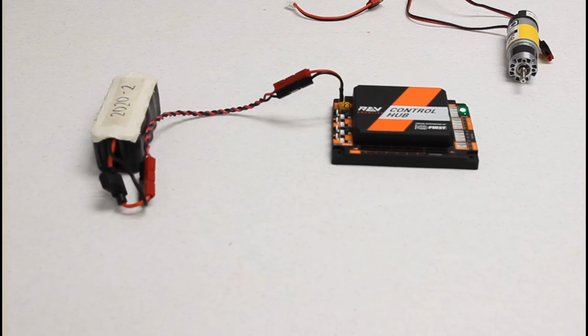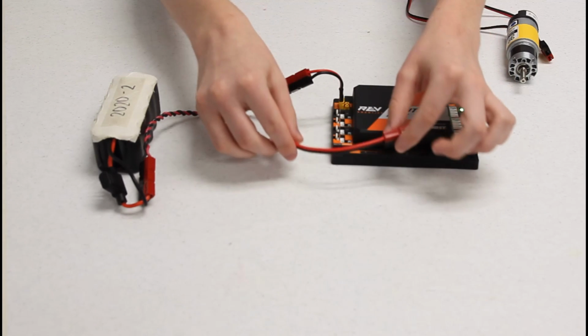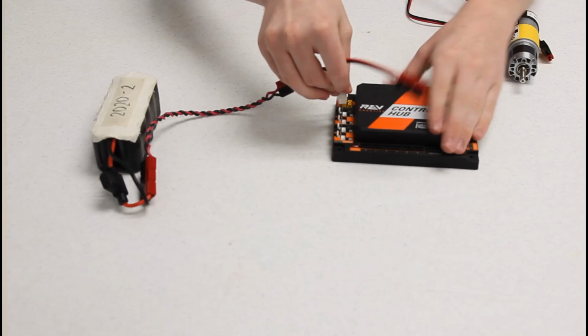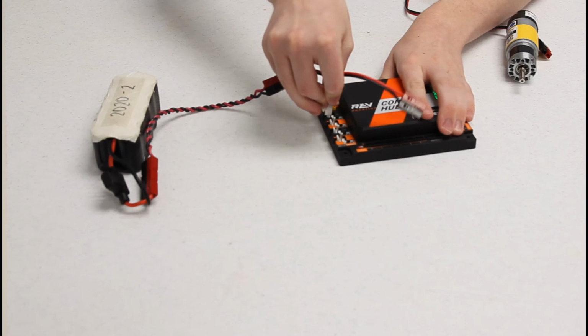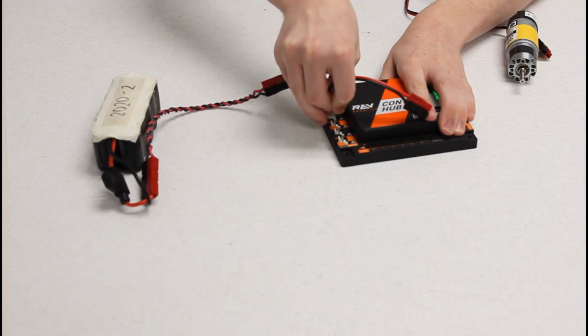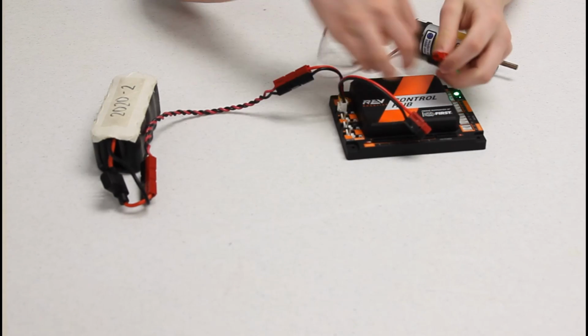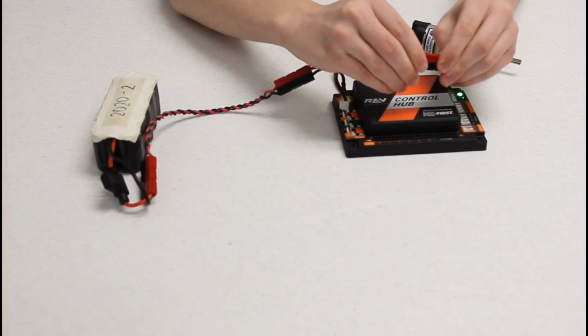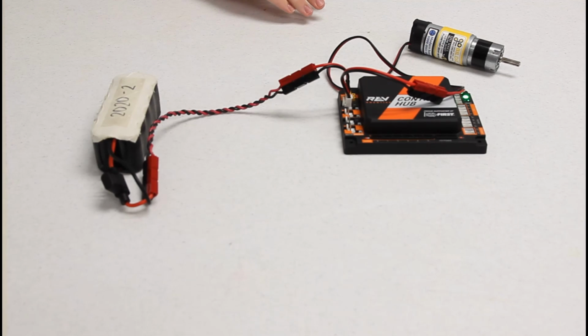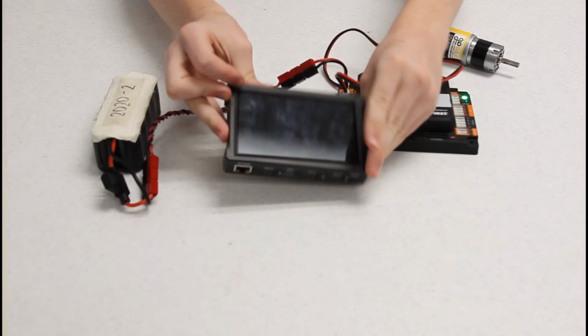So now that our driver hub is set up, we're going to move back to our control hub and plug in our motor. So you're going to need this cable right here, and you're going to plug it into one of the motor ports on the control hub. And once that's plugged in, we can get our motor and plug in the two power poles together. And that's it. Now our motor is set up and we're ready to set up a config in our driver hub.